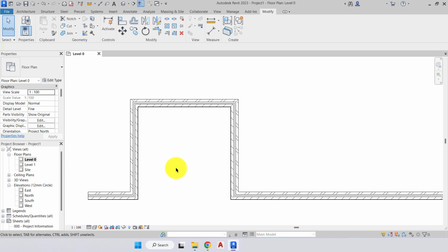The other examples that I can find of where to use this would be if you import an image for your title block or on your drawing, you can scale it up. But again, you can just click that image and drag from a corner to change the size yourself. And as we don't really use scaling in Revit, we simply apply a scale to the view. It's not necessary like it is in AutoCAD.